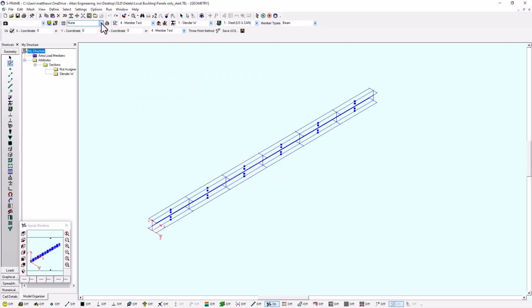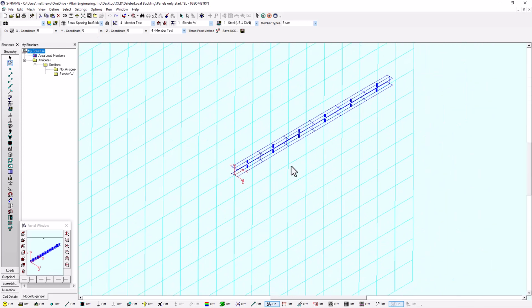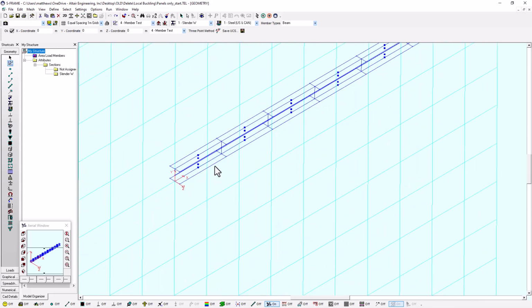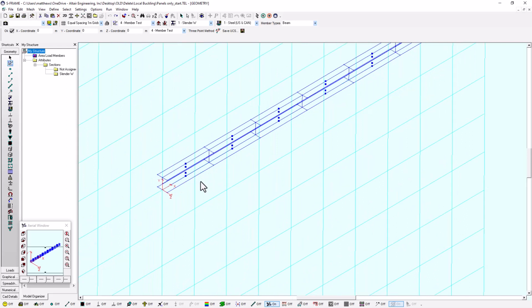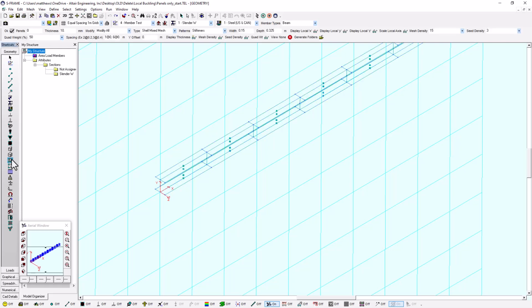And I also want to activate a grid. Now for this application, the grid that we use is not really that relevant, but we do need to have a grid activated for this to work. And this allows me to take advantage of the panel's patterns tool. So if I click on the panel element tool, you notice here that we have this patterns dropdown. It's currently populated with data that I was working with, but I'm just going to set it back to none.